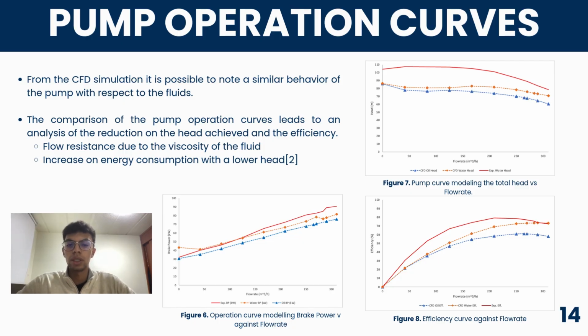When evaluating the results with different fluids, it is crucial to emphasize that fluid properties significantly affect the pump's performance and efficiency. When viscosity is sufficiently high, the flow regime can become laminar, altering the pump's operation. In such cases, friction losses increase, reducing both flow rate and head. Additionally, resistance to flow increases the pump's operational demand, leading to increased energy consumption.